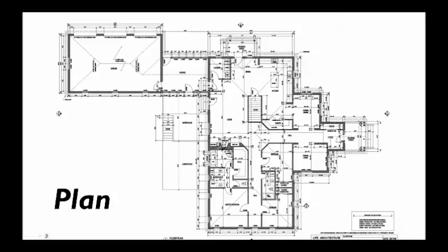The plan view, it's as if you are standing inside of the building, but it's like you're looking down at the floor. That's where we get that idea of the floor plan. But it's like you took a chainsaw and buzzed a horizontal cut, like a horizontal plane, all the way through your building at about 4 feet above the floor and pulled the top of it off.